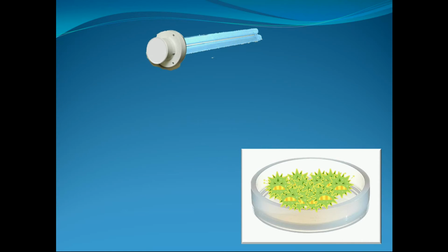With that said, remember we talked early on in some of the early modules about design versus technology. UVC in the right design will kill stuff on surfaces. In another design, it'll do surface kill and airborne kill, but you have to have enough dwell time. If I took a petri dish and put it on the floor here, and put a 45 microwatt UV light a couple feet away, went out and had a cup of coffee, and came back 30 minutes later, everything on that petri dish is going to be dead, right? That's the surface kill we talked about, because it's stationary, it's not moving.